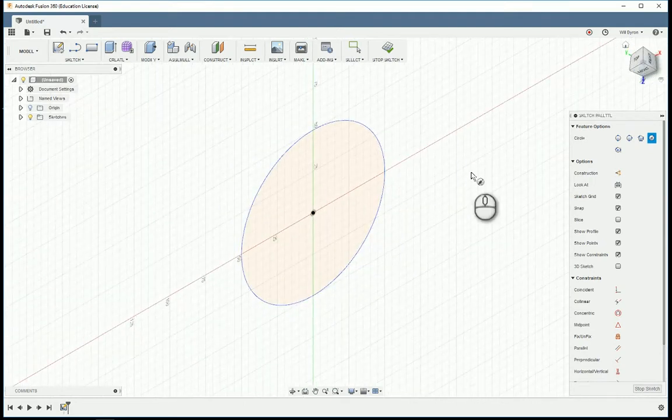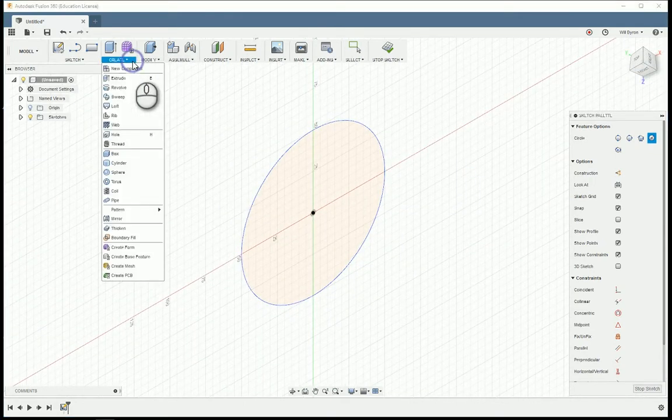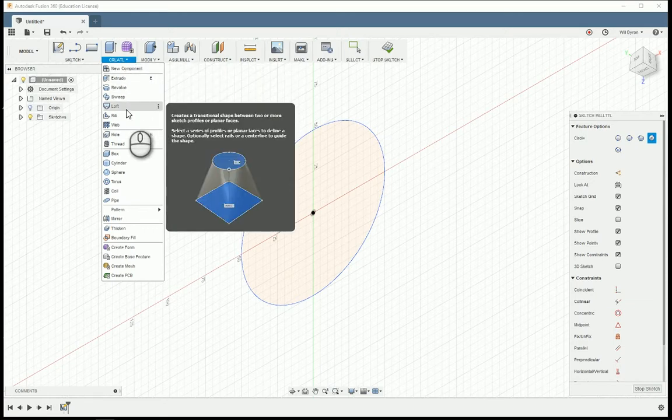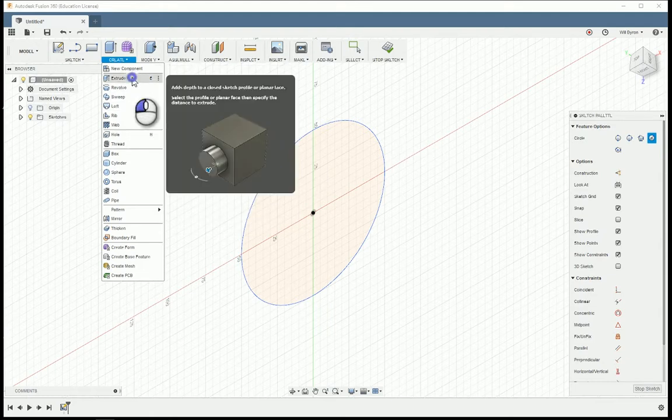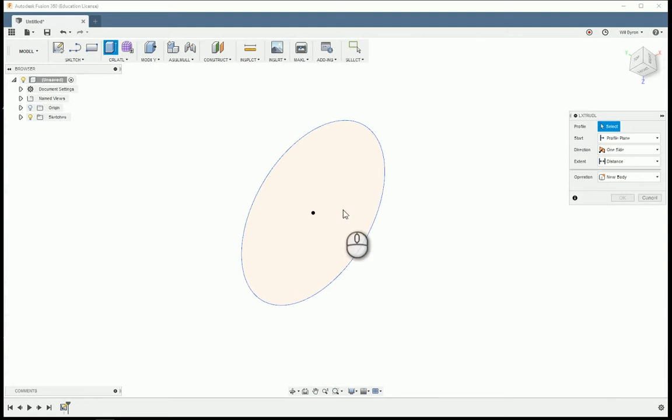Here is the 2D to 3D. This is everything that you're going to find under your Create tool. This is pretty much exclusively, you have a 2D object, you want to make it 3D, or you have like a 1D line, and you want to add some physical dimension to it. And the extrude tool is your primary method of making a 2D object 3D in a single, like an axial direction. It's a lot harder to do multi-axial, you have to do multiple sketches for that.